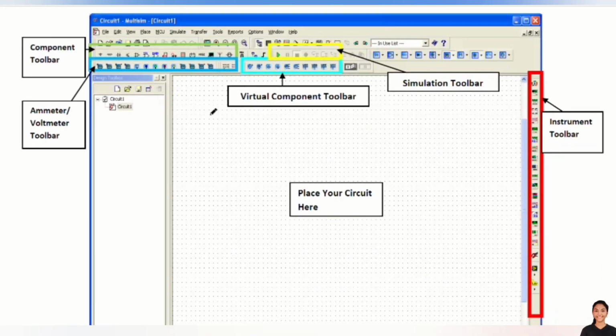If you see the interface, here we can see the ammeters and the voltmeters required, and here we can see the components toolbar, or you can click on Place and then open Component and search for the component. Then whatever component you want, just drag it and press the right button on the mouse. Thus the component will be placed on this breadboard. This is like a breadboard, like the ones we see in the EDC laboratory or the LECA or the PDC laboratory, right? We can simulate the circuit diagrams which we use in the EDC, LECA and many other experiments.